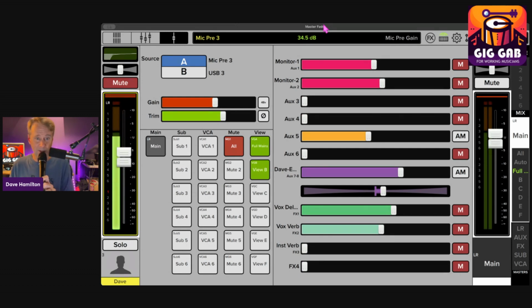A lot of condenser microphones, a couple dynamic microphones need it. Some other things need it. Some, you'll know. It'll say so on the device or in the manual for it. Or if you plug it in and you don't get signal, there's a good chance that it needs 48 volts of phantom power. I always hesitate to say, turn it on and try, because there are some devices, fewer and fewer as time marches on, where that 48 volts would damage them. The mic that I have here will not be damaged when I add phantom power, even though it doesn't need it. It's a Heil PR37, but it doesn't need phantom power, so I'm going to leave it off.